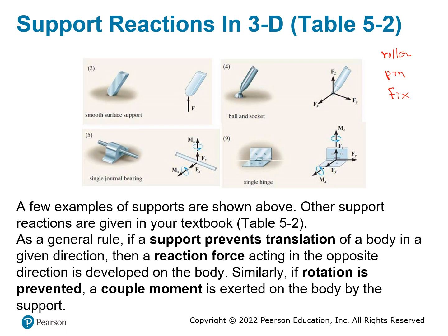Let's look at this one here. It's like a bar with a very smooth bottom, supporting things, and this allows only a reaction force perpendicular to the contact surface. If the surface is the ground like this one, then the force is perpendicular to the ground.